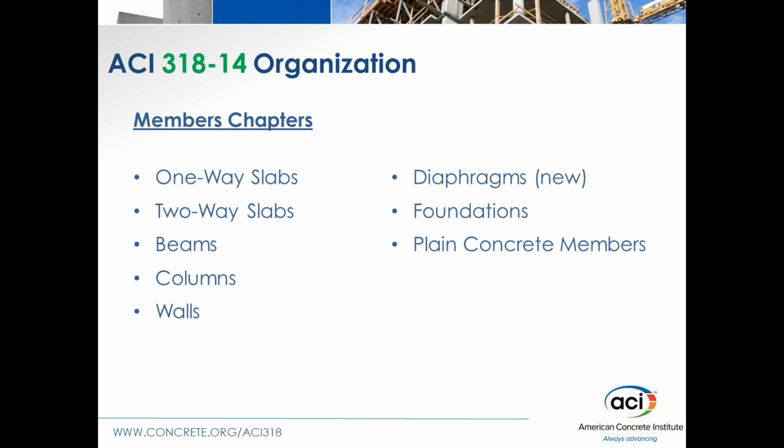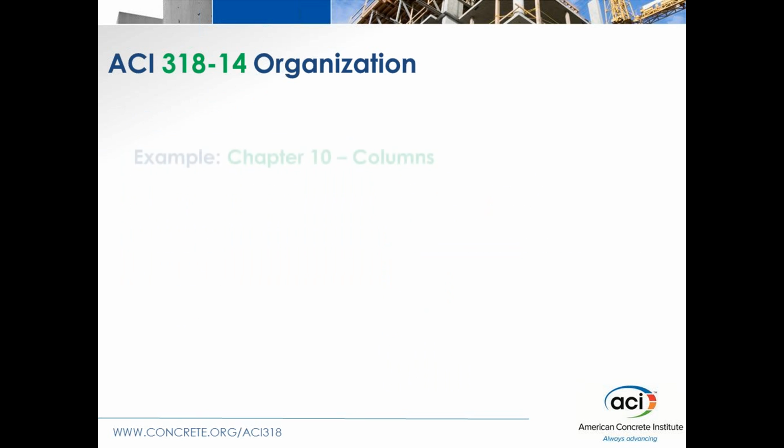One new chapter is called diaphragms. When we were putting this information back together, it became clear, particularly with that Chapter 4 and how lateral loads were placed on a building, that we talk about slabs, which are really gravity load slabs. In the seismic chapter, we talk about having collectors and diaphragms, but we really didn't have a chapter on just diaphragm design and detailing. So that is a new chapter in this code, a chapter on the design of diaphragms.